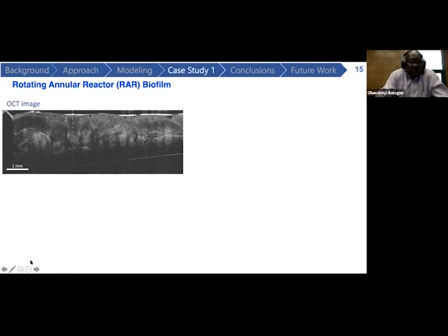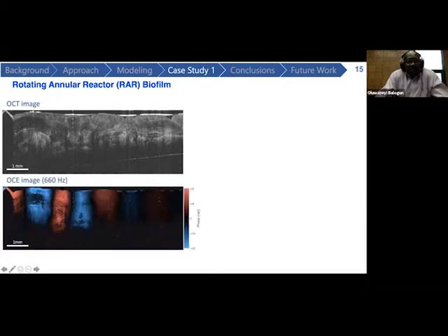When we make our OCE measurement, so this is an OCE measurement at 0.6 kilohertz, you can actually see the same contrast reflected within the OCE images, and the reason is because each pixel point is directly proportional to the out-of-plane displacement of the sample, in addition to the local index of refraction. So these two images are superimposed on each other. And the other thing we notice here is not only do we see the stripes, but also the intensity of those stripes decays as a function of distance due to viscous losses in this material.